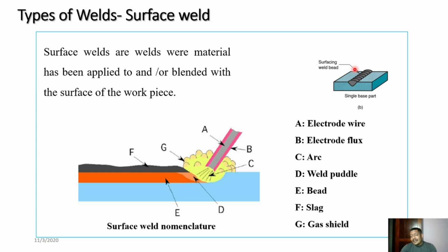Normally the first trial of every welding, we call it bead on plate welding. It means that the welder is performing a test of the set parameters on a used plate to ensure that the set parameters, and the robotic arm movements if it is robotic welding, are all correct.